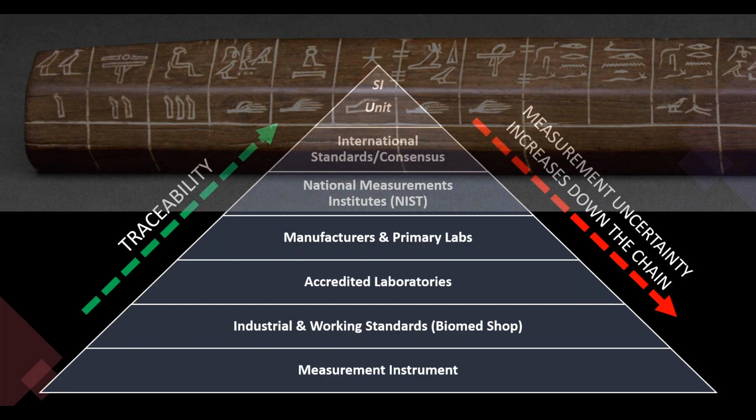We have an AM probe thermocouple meter as well. Its accuracy is really close to the Fluke 52, except for this one we're using the air bead probe, and the air bead probe is 1.8 degrees. So now we have a little bit more than 2 degrees for our total error. We have a ThermalWorks platinum resistance thermometer. Its accuracy is 0.05 degrees Celsius.